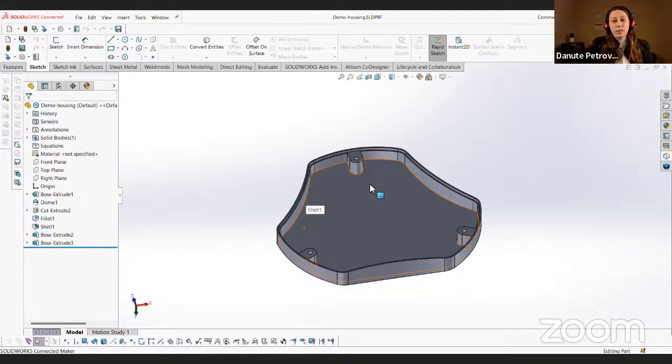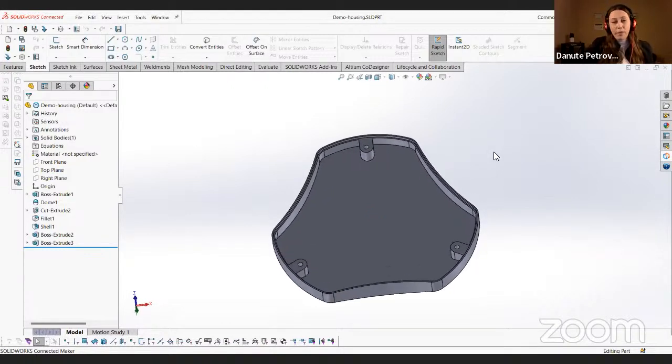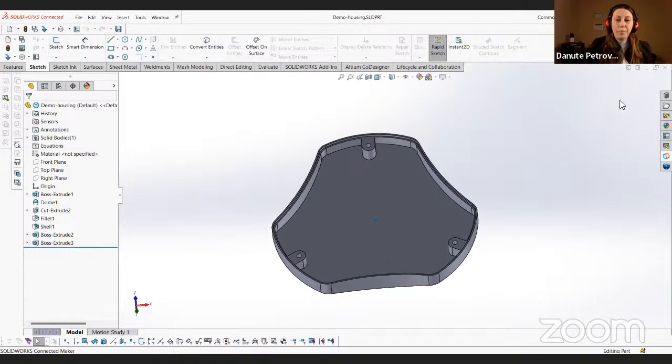And in SOLIDWORKS, this is like less than 5 minutes work. For them, it's a few hours. So either you create the project first and shape the board for them, or they make you a simple board, you pull it, shape it, and push it back. In 5 minutes, you can have a perfectly shaped board, and everybody is extremely happy.